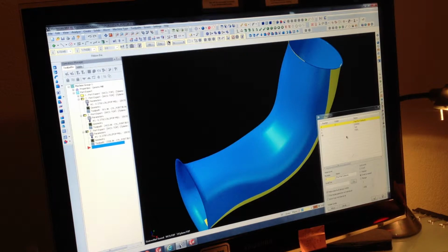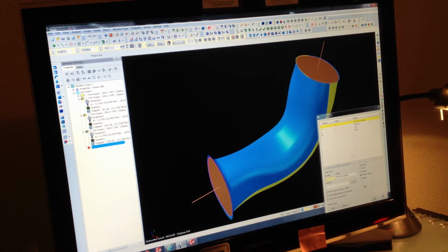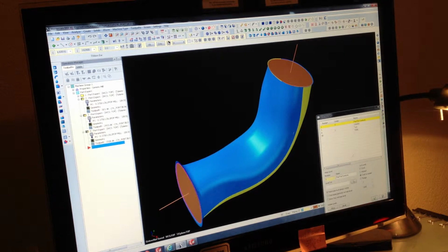So what we did, I'm going to turn some levels on. Okay, and go here, try to fit the screen, and we're going to go a little to the left. Okay, so what we did last time, we created a curve on both ends of this port, right on top of the lip, on the flange, outside flange, right there. So you create a curve only on one edge. There's going to be a bunch of little segments here. Sometimes you have to chain and watch out for smaller portions. Keep chaining it around till you finally finish the chain and close the chain.